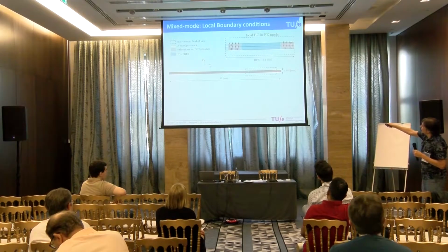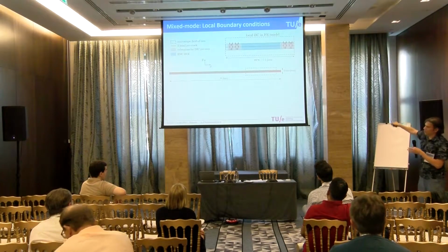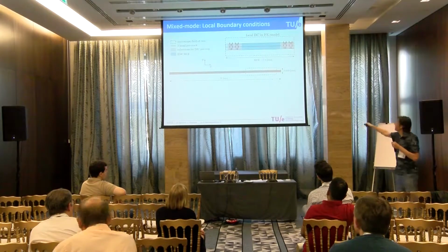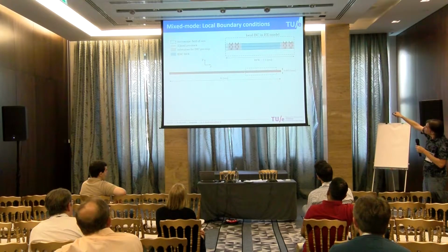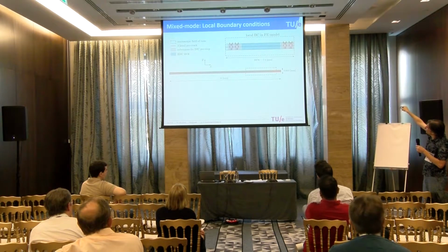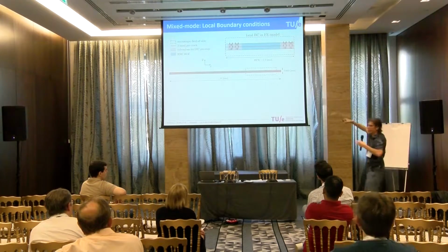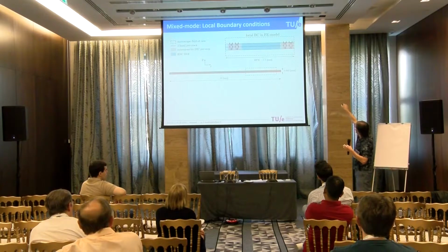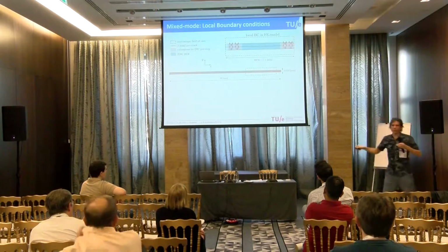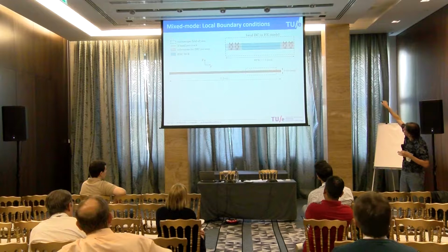So in mixed mode, now this is flipped again. Now the crack is coming from the right. So if you think, okay, what do we need to enforce? Now we also need to have the shear in there. So we do need to add additional degrees of freedom on both sides. And the crack is actually running completely through this.